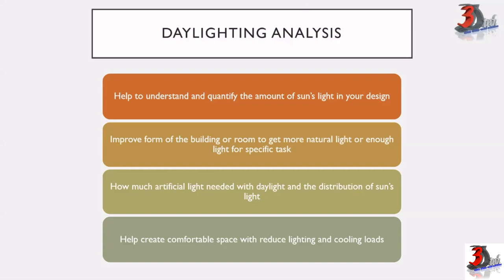Later in the design process, you can really hone in on the daylight to test for interior visual comfort. This is where computer simulation and lighting consultants typically will come in. Often this work involves quickly testing different design parameters like shading features, glazing properties, and window placement. Simulation results are usually calculated on a workplane based on a specific vantage point, which is our head height for a worker. Okay, so we're going to take a look into this in a moment.